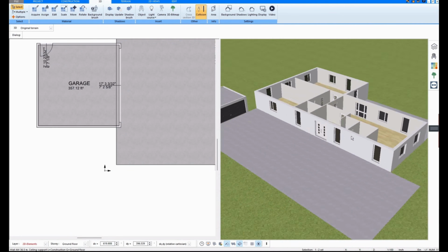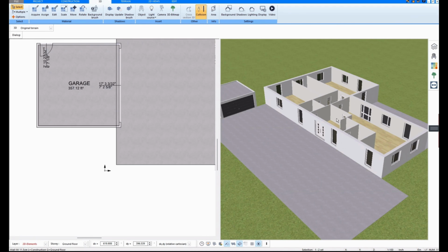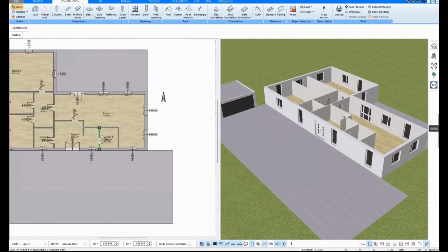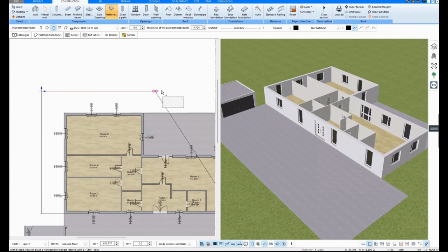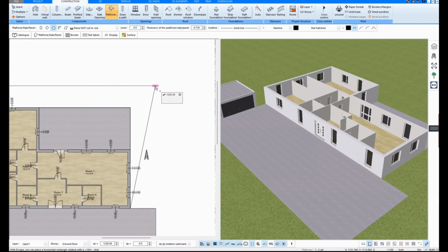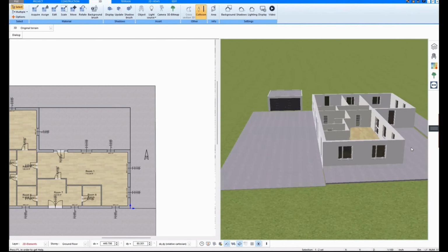So, now I'm planning another floor. No, wait. I'm planning the garden now. I use the plate function as a polygon again and draw a garden around the house. In other words, an area that I then assign as a garden.